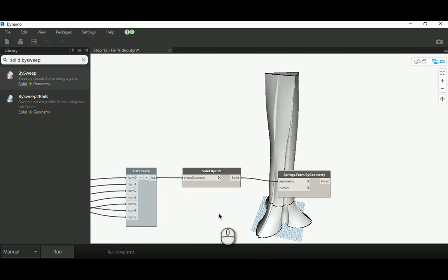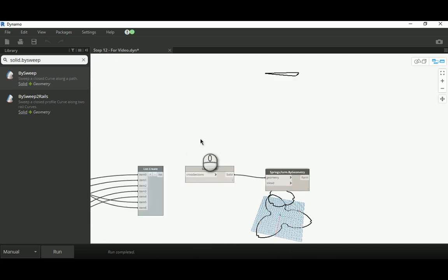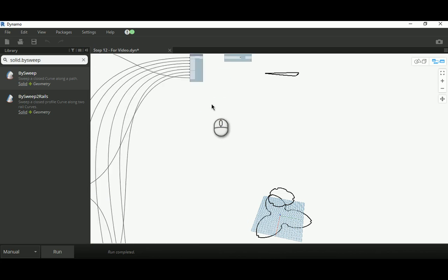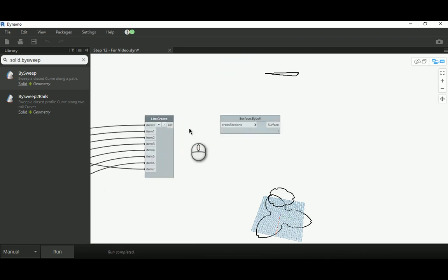And the lower part, it's just making a solid, so I'm just going to cut that out and then go up and make the second part here, and create a surface out of that. So probably we need to activate the preview and then regenerate the whole thing, and you're going to see the previous part stops here and gives us the solid, where we get the horizontal elements.